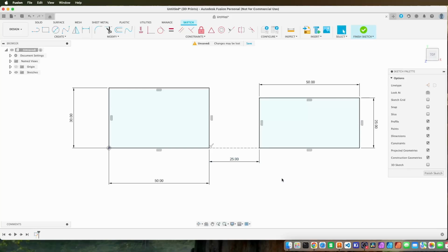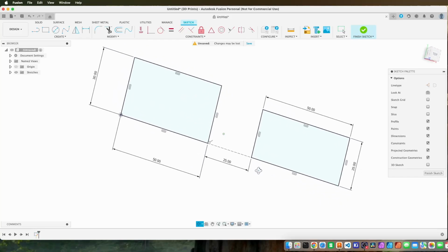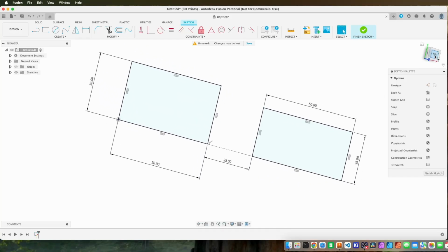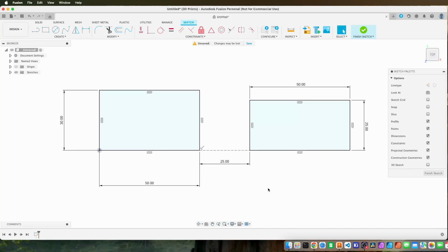And then because we used the top view, we're gonna click on the top and we'll get back to the original sketch view. For the orbit, you can also hold down shift on your keyboard and press down on the center wheel, and that will do the same. So you have two options there. So let's go back to the center where we were, and that's the basic tool movement of Fusion 360.